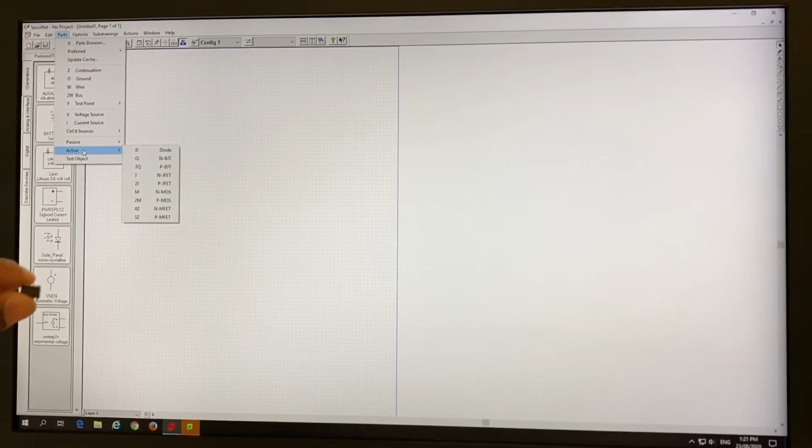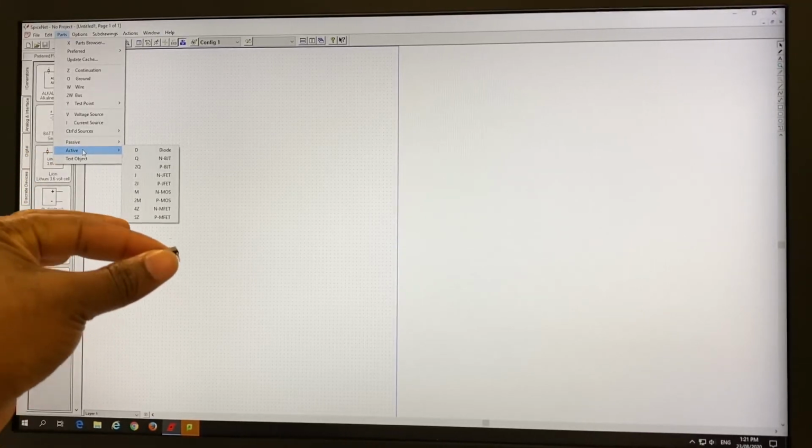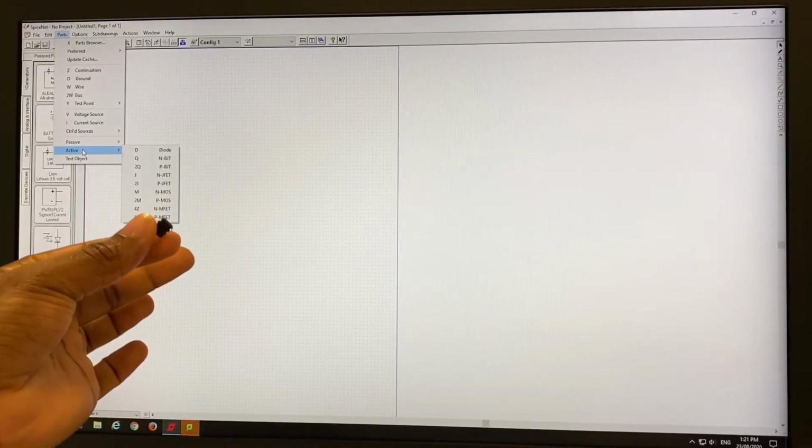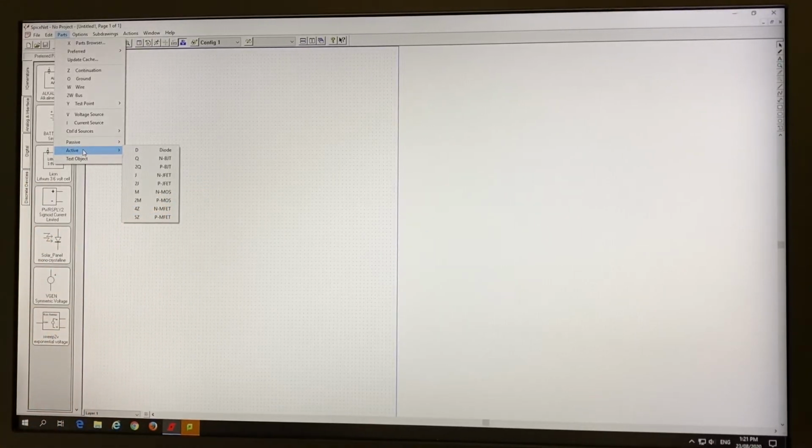Like this is an op-amp I'm holding here, an operational amplifier. So this is a 741 operational amplifier. It has got legs. If you can see, there's some legs there, about 8 of them. On these legs, there are bias voltage legs, which should be pin number 4 and pin number 7. One has to have plus 12 to 16 volts. The other one has to have minus 12 to minus 16 volts. So those two legs have to be connected and biased.